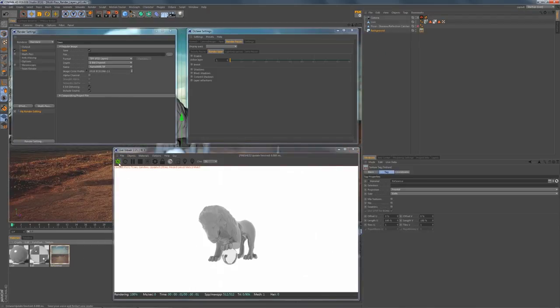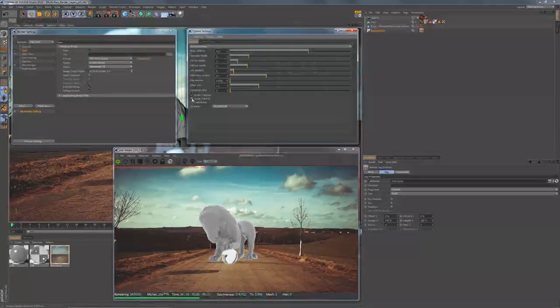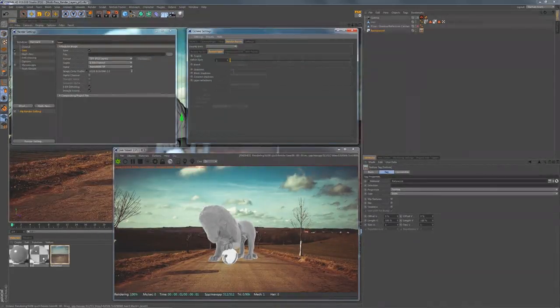If we now press render, nothing happens, and the reason is that the background object and the render layer system actually require an alpha channel to be enabled. Please consider I have adjusted the camera in my composition to roughly match the perspective seen in the image.